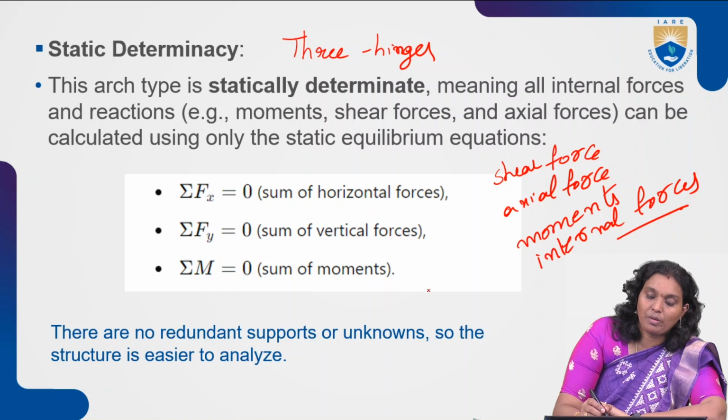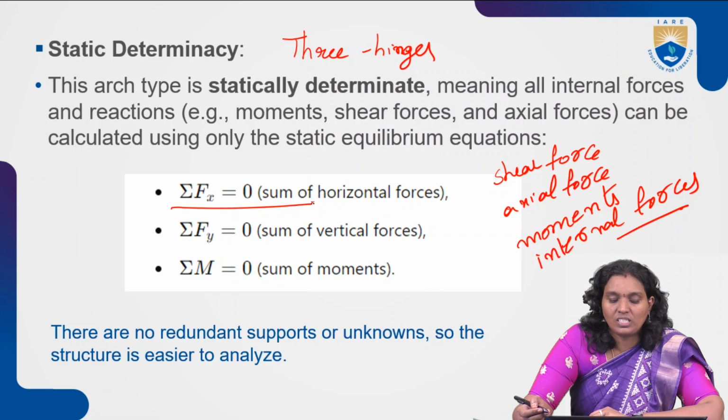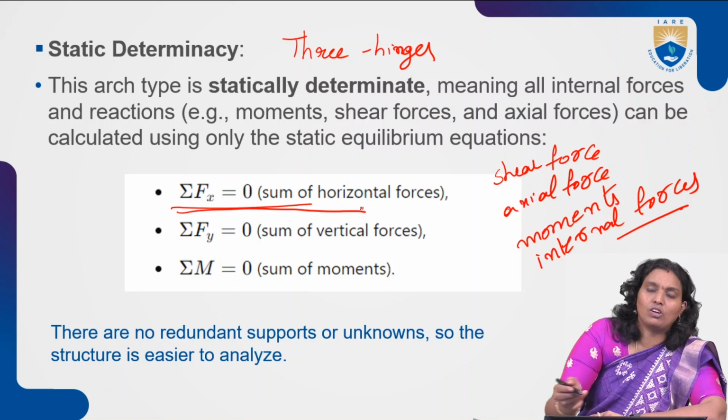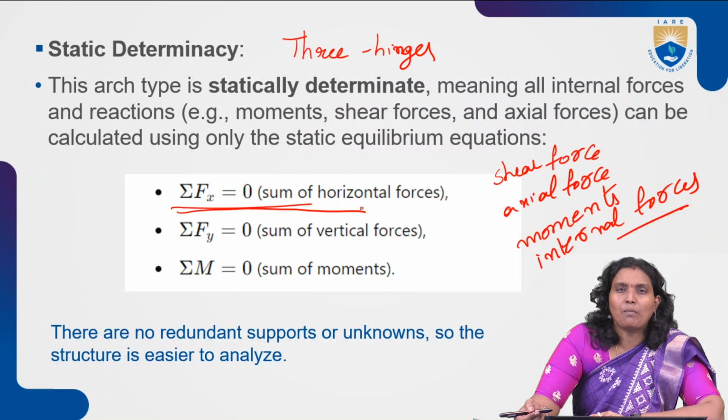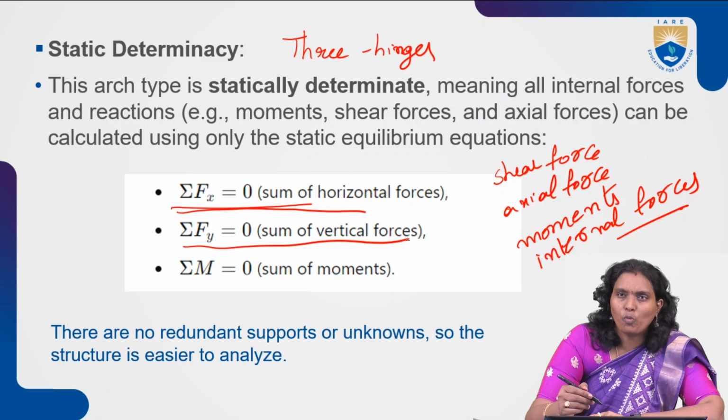Those static equilibrium equations are nothing but the sum of the horizontal forces involved in that particular given arch, irrespective of the shape and size of the arch. In three-hinged arches, the sum of all horizontal forces is equal to 0, and also the sum of all vertical forces is equal to 0, and the sum of the moments as per the load conditions.